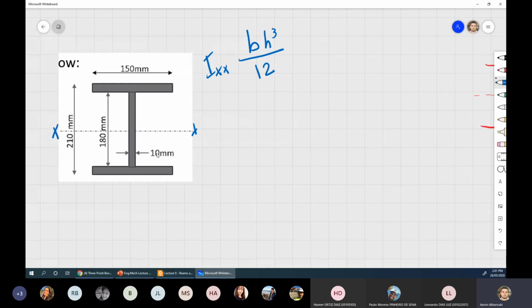So in this particular shape, what I can do is take one large rectangle, and the centroid of that rectangle is here. Assume it's all made of steel, but in reality, that's not all made of steel. Minus, I can take this rectangle here, let me draw it in a slightly different color, minus this area of air. Look at this rectangle here, and the centroid of this rectangle is again here on the neutral axis, minus that too.